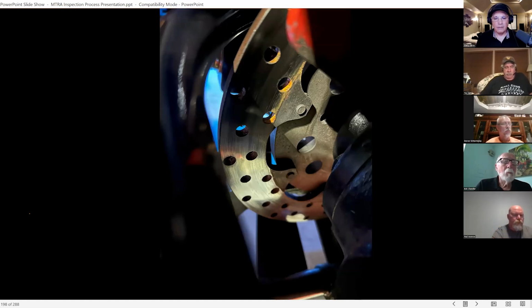I mean, obviously that creates problems on every level: building damage, truck damage. What happens when you lose a bolt on one of these is, as the caliper clamps a spot, and if it's missing a bolt, the rotor wants to pull away, and it'll actually peel the rotor right out.